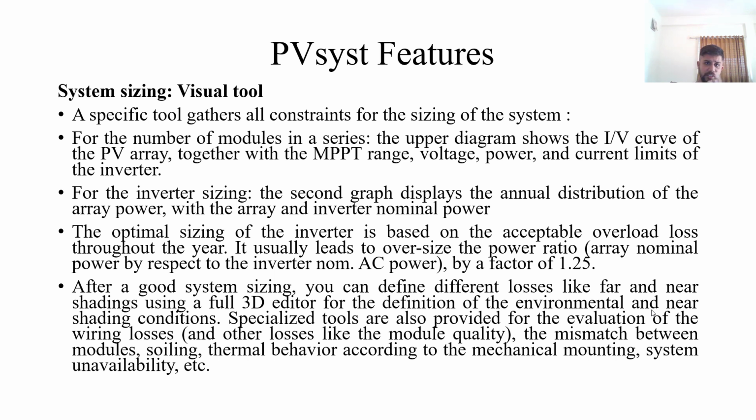Now, another PVsyst feature is system sizing. It gives us the liberty to use this tool for the available size. A specific tool gathers all constraints for the sizing of the system, like the number of modules in series. The upper diagram shows the IV curve of the PV array together with the maximum power point tracking range, voltage, power and current limits of the inverter you have chosen.